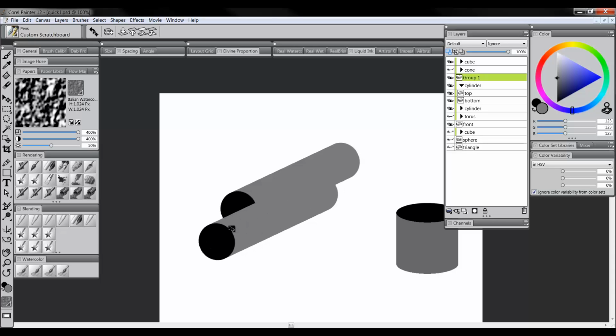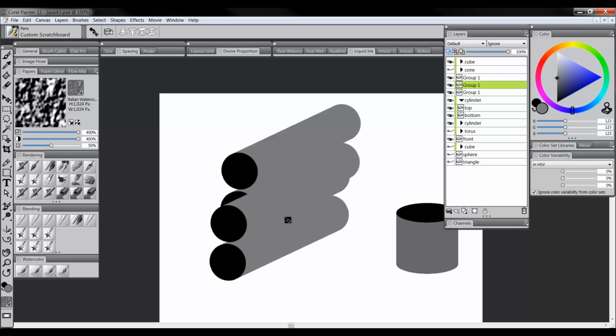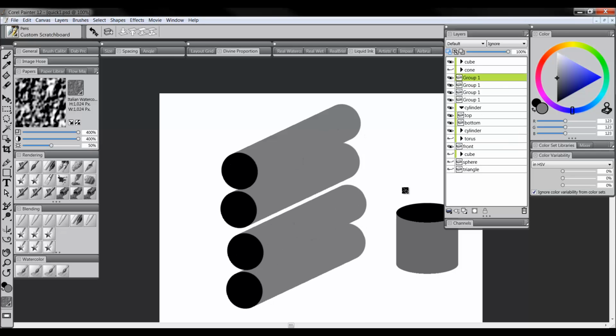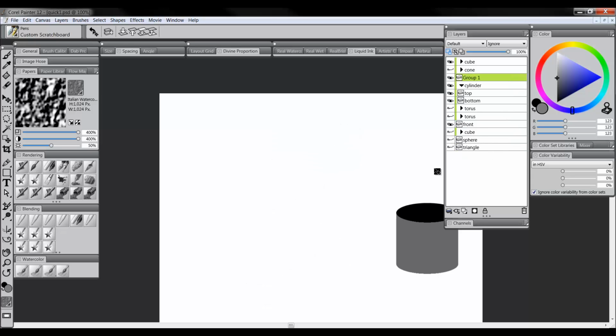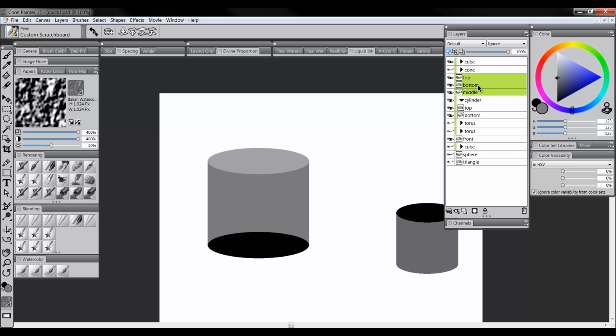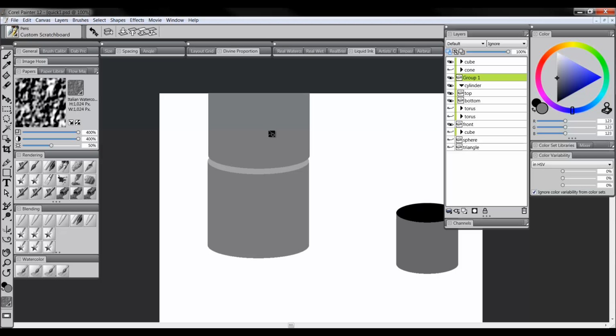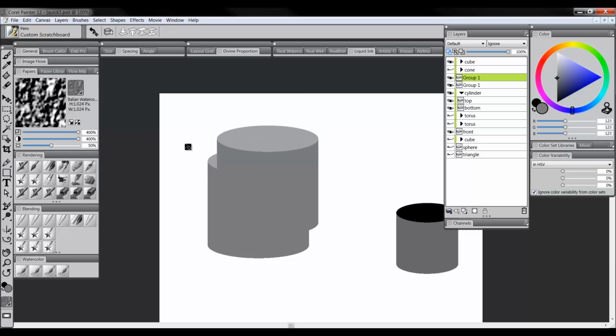And as I mentioned before, you can duplicate. So if you wanted to make some more complex thing, it's pretty easy to do. Or if you wanted to make some sort of stack or something, that's pretty easy to do also. Again, group these and merge them, and then I'm holding Alt on my keyboard to do these duplications by dragging, and let's scale this down a little bit.